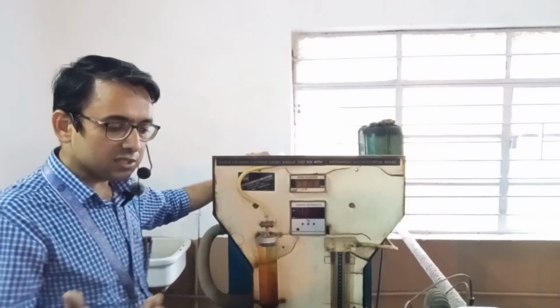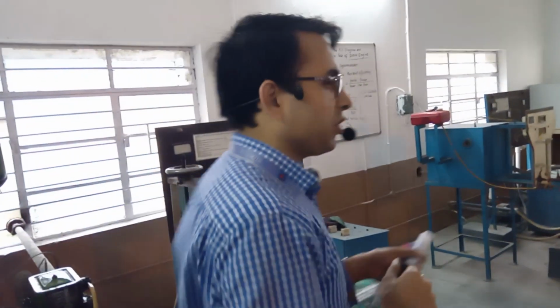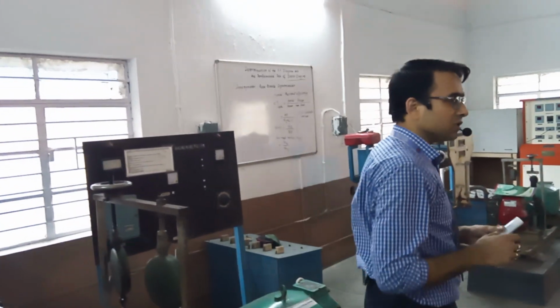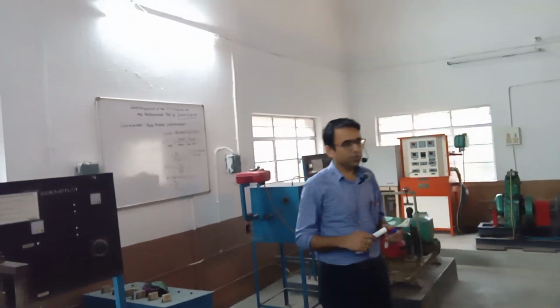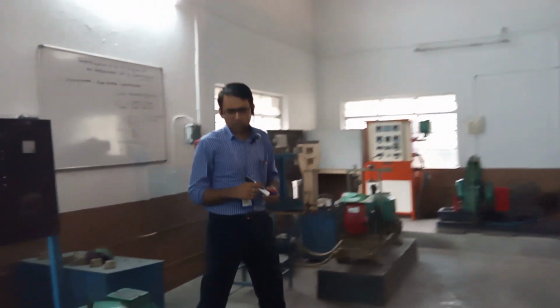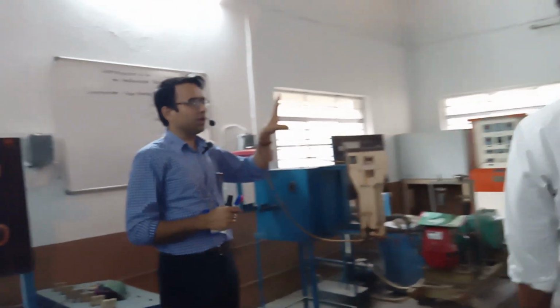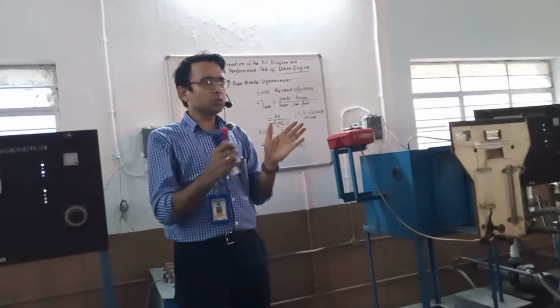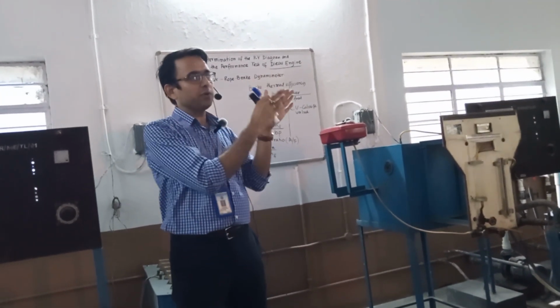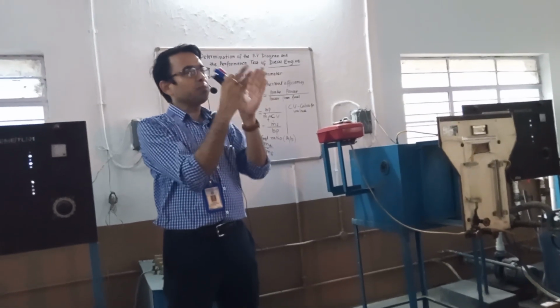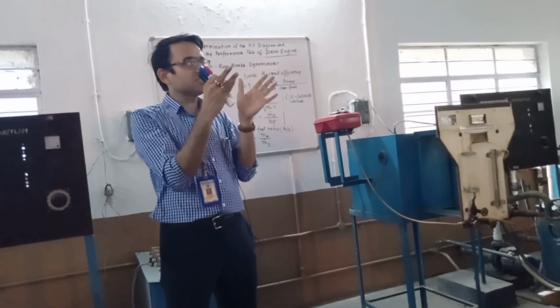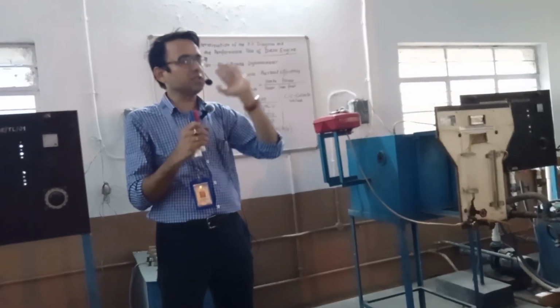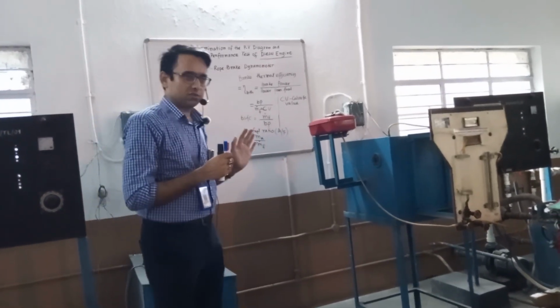Now the pressure difference and the velocity in the orifice are connected, because in the Bernoulli equation there is flow energy, kinetic energy and potential energy. They are related. The total mechanical energy, that is flow energy, kinetic energy and potential energy, the sum of these terms is constant along the flow path if there is no loss.